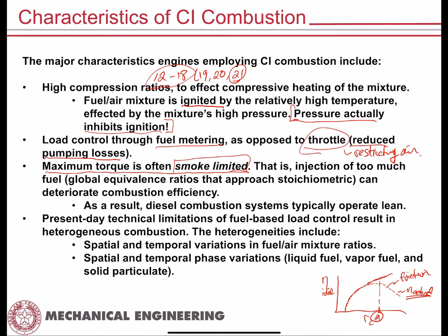So you have penetration, you have breakup, and then once you have breakup, you have another scale of fluid particle breakup, which we call atomization, right? So you take that spray that's breaking up and you break it up even more, so that you have a larger volume of liquid fuel composed of smaller and smaller liquid fuel droplets or particles, okay? So penetration, breakup, atomization, and then finally the last one is vaporization, okay?